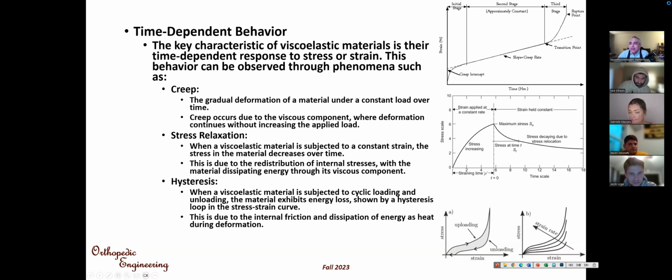And at the end, the creep leads to failure and rupture. So creep is a form of deformation. We will see it in our biomaterials when we use them in joint replacement, because they are under constant load, and this constant load gradually over several years changes their shape.